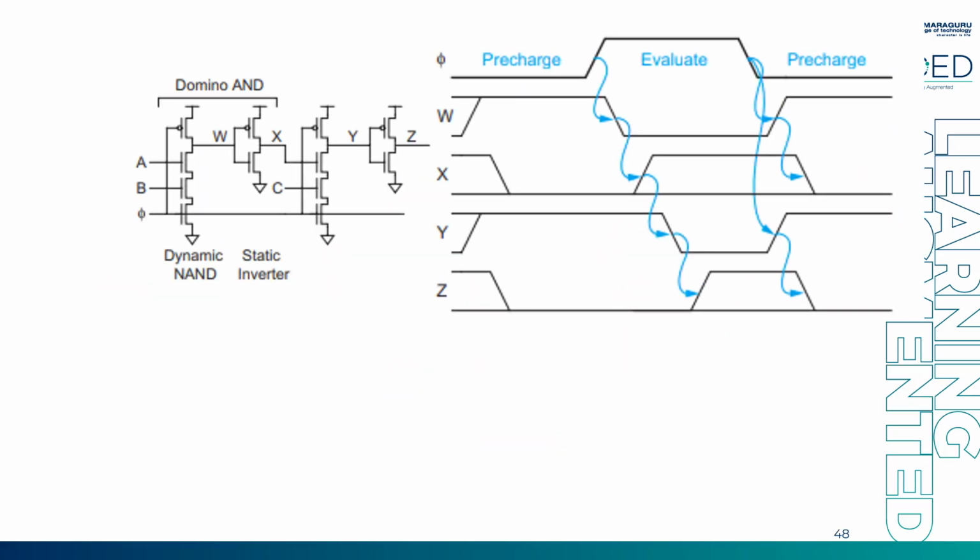So this is an example which I have stated. You have one more domino CMOS logic involving two stages cascaded with each other. As seen in the last slide, you can see how pre-charge happens parallelly and how evaluation happens sequentially. So this is how evaluation happens sequentially. So first evaluation phase, second evaluation phase, third evaluation phase. So this is how it happens.